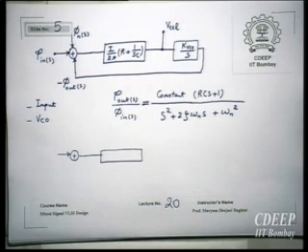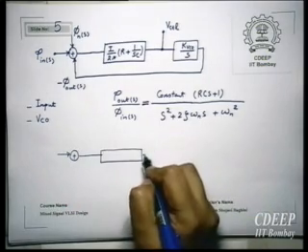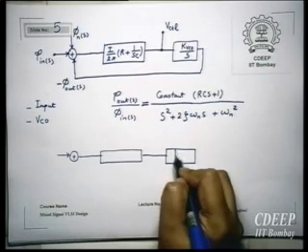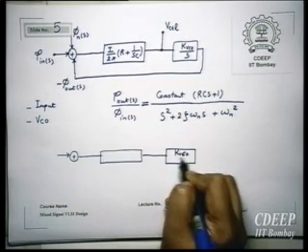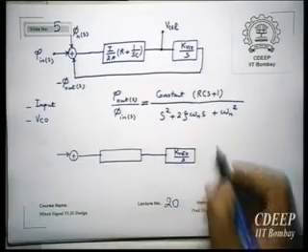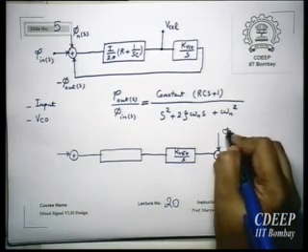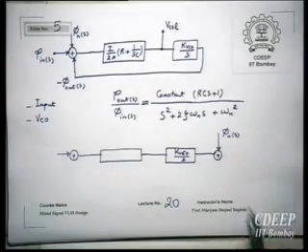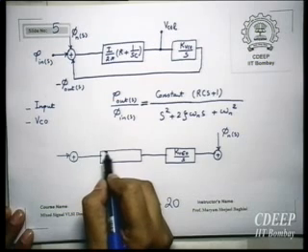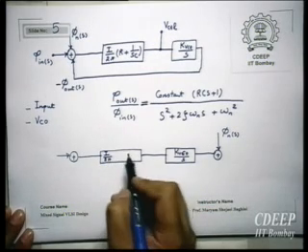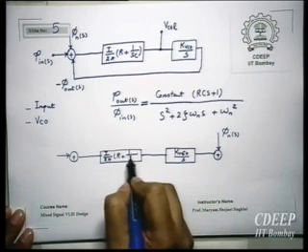Therefore, it will be added at the output of the VCO, which is the output phase, so I add it there. So here I put another noise source, and then here there will be phi. We just want to see what the response of the PLL loop will be to these two types of jitter.